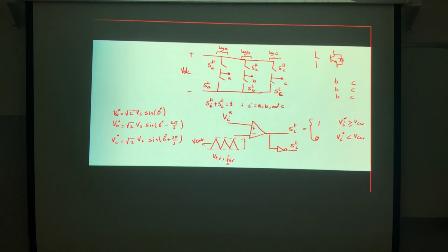For example, if I'm restricting the carrier to be from -1 to 1, is there any meaning for VI reference to be 1.3 or 1.6 or 1.9 or 2? The switch is closed. But I will not allow operating higher than the carrier. Why? Because it's a saturation.